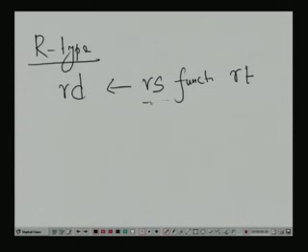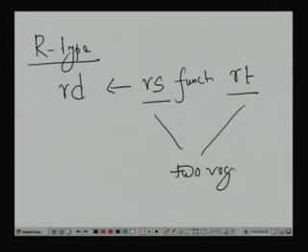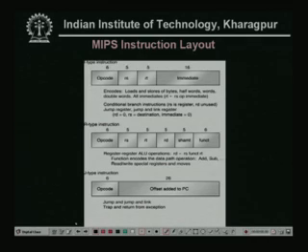See, these are again 2 registers, the content of 2 registers is operated on by the function, and the value is moved to RD. Function encodes the data path operations: add, subtract, read write special registers and moves.